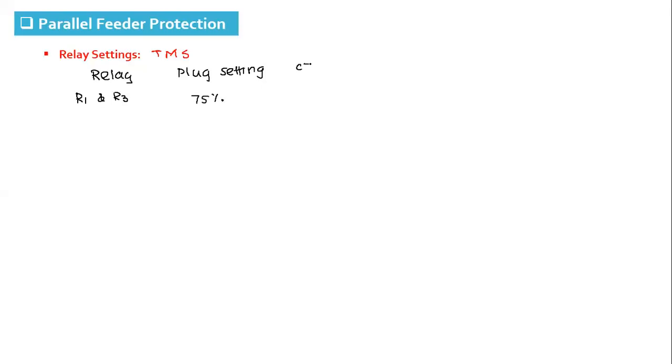Its CT primary rating is 2 ampere, and therefore the pickup of R1 and R3, 75% of 2 ampere, is 1.5.